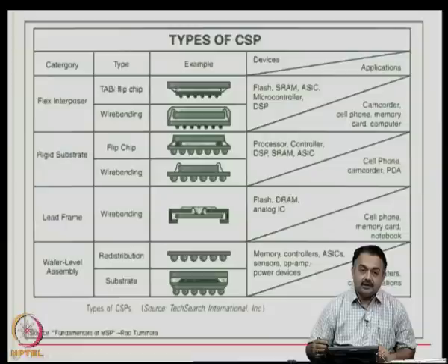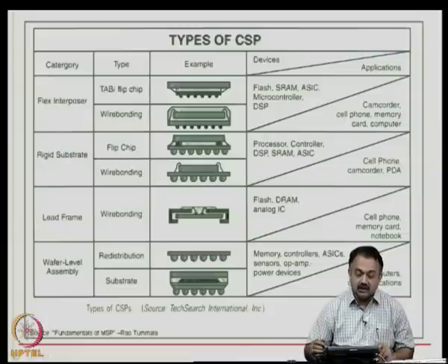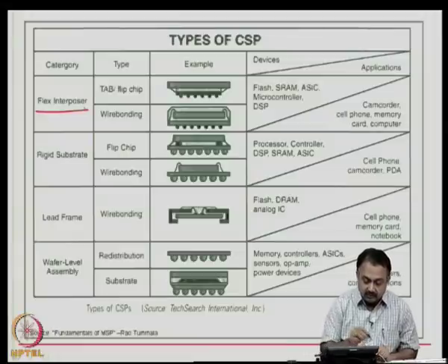The die and the substrate together can undergo changes during thermal cycling or expansion and contraction of the entire set of materials, the silicon die, the organic substrate. So, in order to avoid die crack and warpage of the substrate, you would rather use a flex interposer.